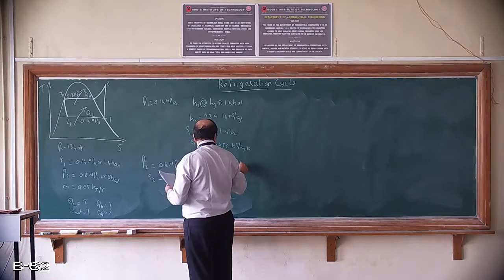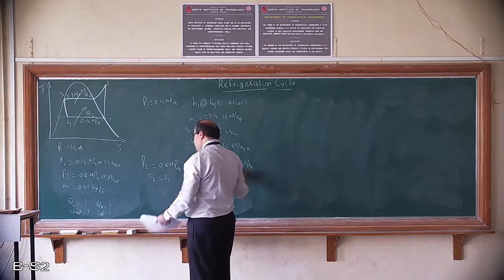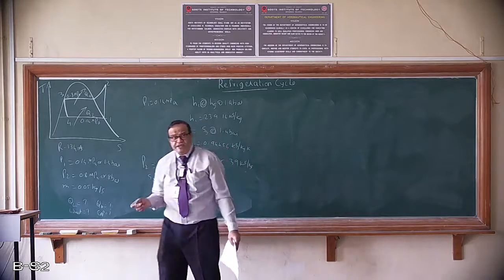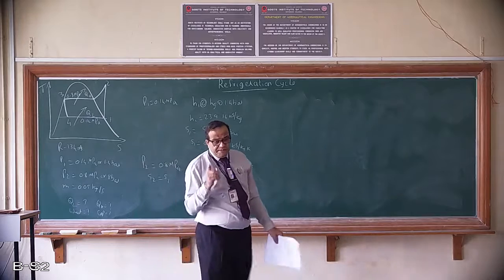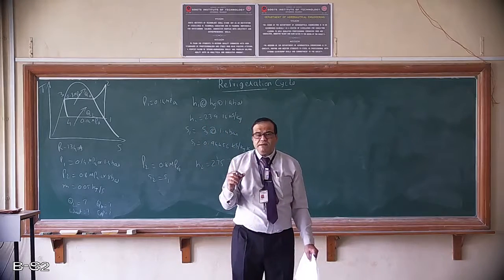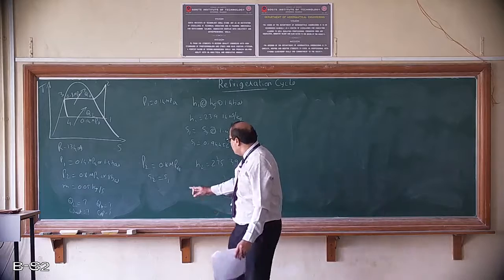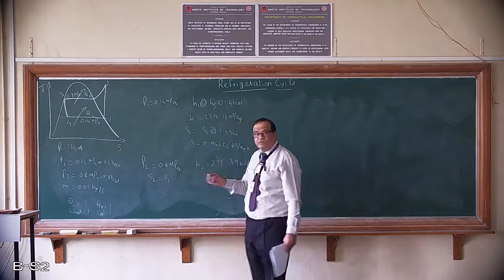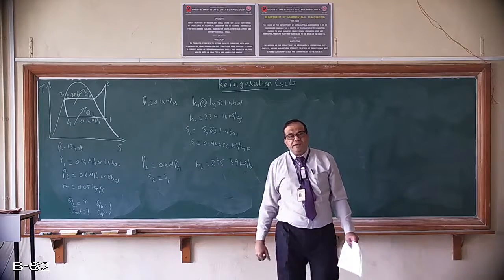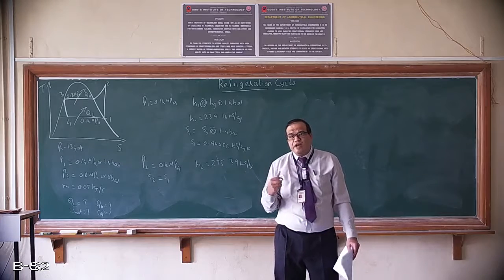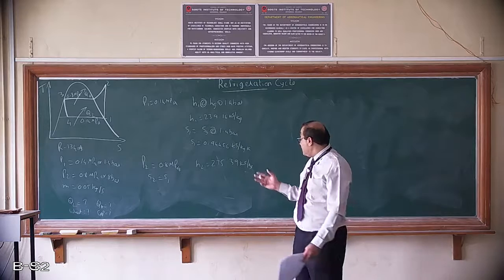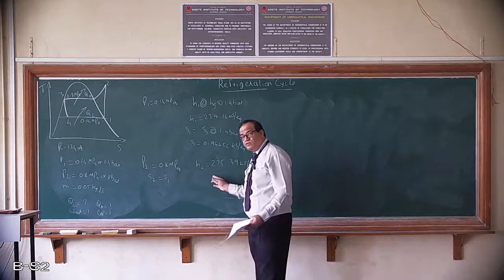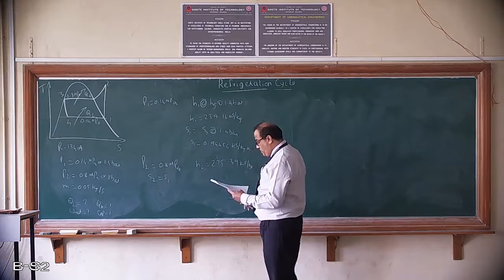So this will be kilojoules per kg. So refer table 20, go to 8 megapascal pressure on the top corresponding to S2 value. Very near to that we need to take the H2 value, which is given there, or this is between two values, you can interpolate and get the exact answer for this. That's also possible. Now we know this.